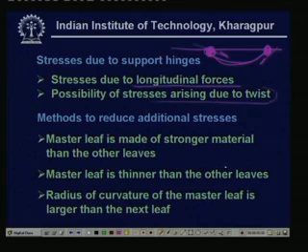What are the methods to reduce these additional stresses? The methods are something like this. The master leaf is made of stronger material than the other leaves. Okay? This is one way.